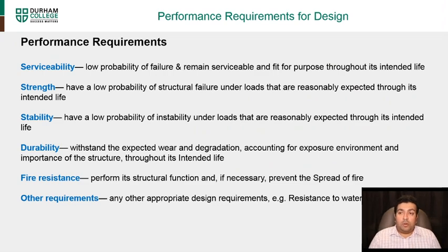So the performance requirements that we discussed: you have to have serviceability. You should have a low probability of failure and remain serviceable and fit for purpose throughout the intended life. Then you need strength: a low probability of structural failure under loads that are reasonably expected throughout its intended life.